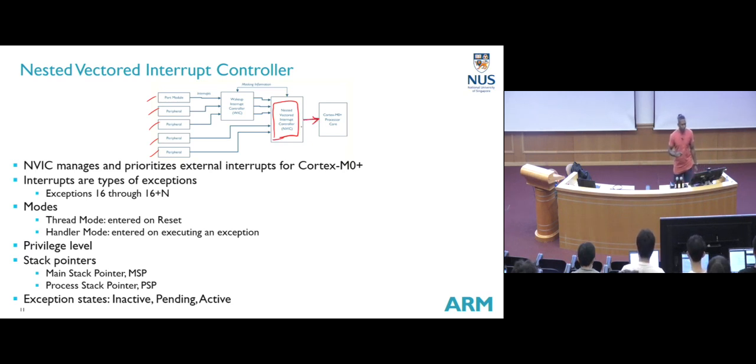Here you can also see there is a wake up interrupt controller. So what is this wake up interrupt controller? It is the ability for you to wake up your system if you put your system in some sleep mode. If you remember, we can put a controller or a device into what we call a sleep or deep sleep mode, where it consumes very little power. Then how do I wake up the device? I need to send some wake up signal through the interrupt, and some of these peripherals will have this ability.